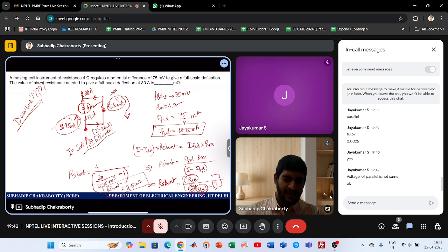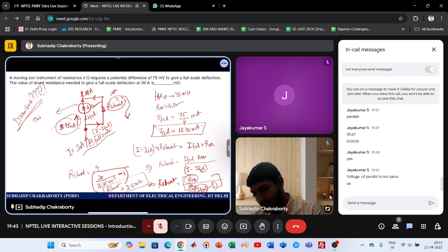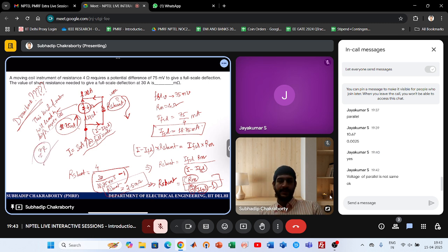By doing so, when you are trying to divert the remaining amount of current through the shunt resistance, which is of a low value, what cost do you have to pay? This kind of meter will lead to high power loss. I square R, right? Because a high amount of current is diverted through a small resistance, it will obviously lead to a power loss, which is undesirable.